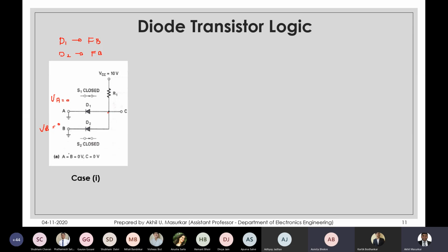Because the anode is connected to the positive and cathode to the negative. Okay, don't say positive and negative, because as far as I can see, cathode is connected to ground, it is 0. Yeah, sorry, ground. Okay, so you can say that the potential difference between the anode and the cathode is 0.7 volts, or probably more than 0.7 volts, and that is why diode D1 and D2 are on.